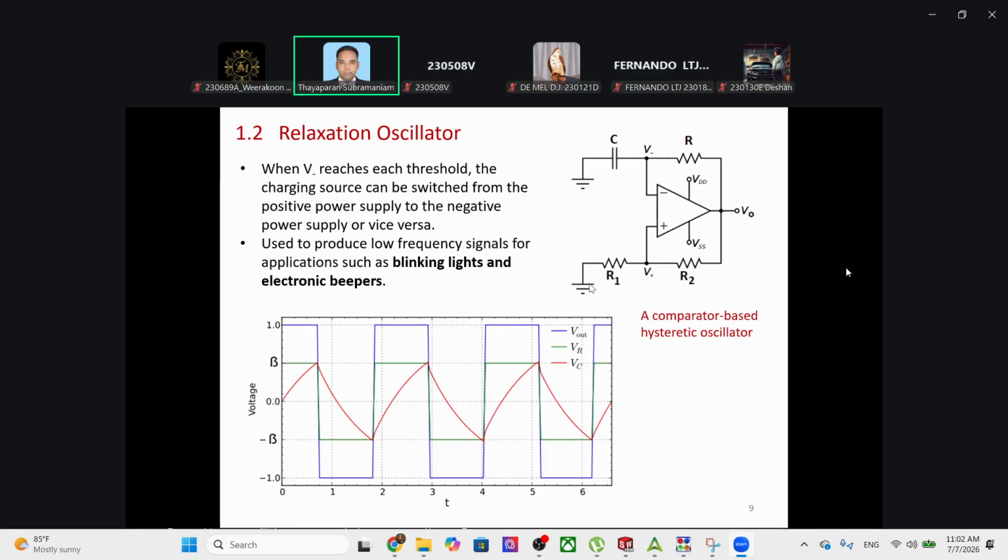Here we have to have a dual power supply if you say this is ground. Or else you may have a 0 to 5 volt supply with 2.5 volt as the mid value. You have to use another potential divider for 2.5 volt, or a Zener diode at the mid value. If you use a Zener diode to get a reference midpoint, then the power consumption through the Zener diode has to be considered.